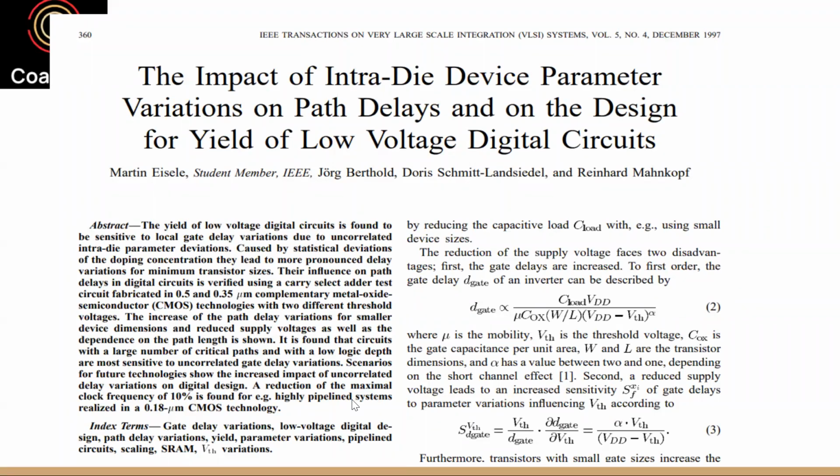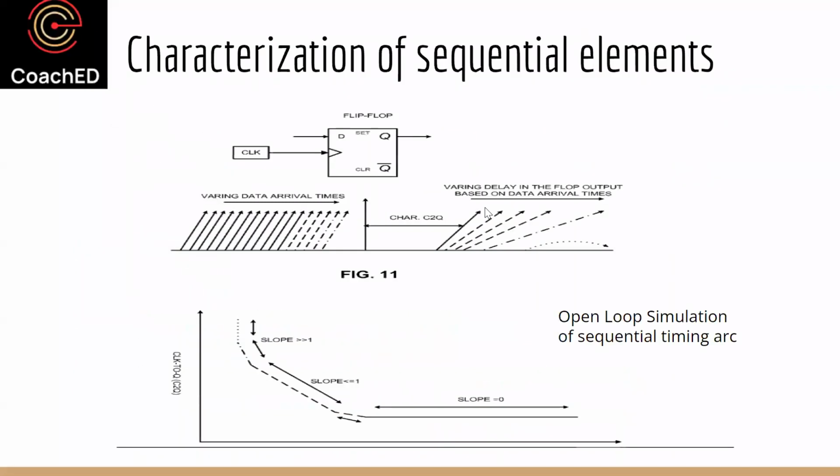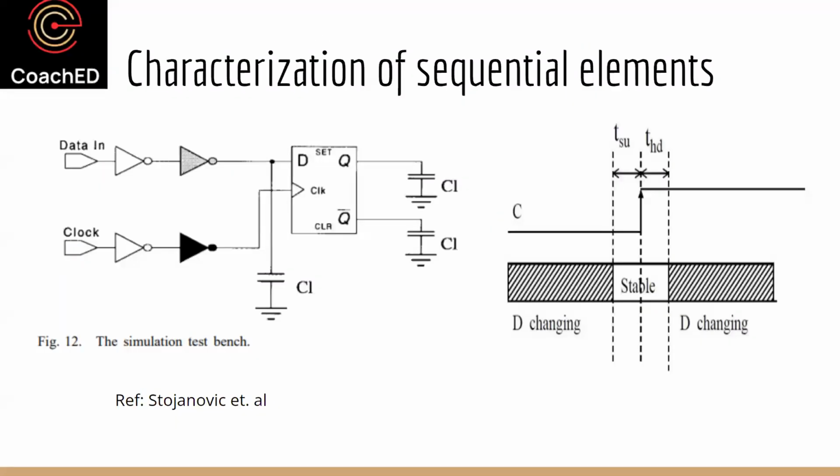Yes, the size of the gate can lead to an increase in load capacitance, as we saw earlier. I think Pawan was asking what is the effect of load, and we talked about this in the previous lecture, where I showed how the overall load on the output is not just the load coming from the other gates which you're driving and the wire, but also the gate's own self-loading from its own diffusion capacitance and its own wire in the layout.